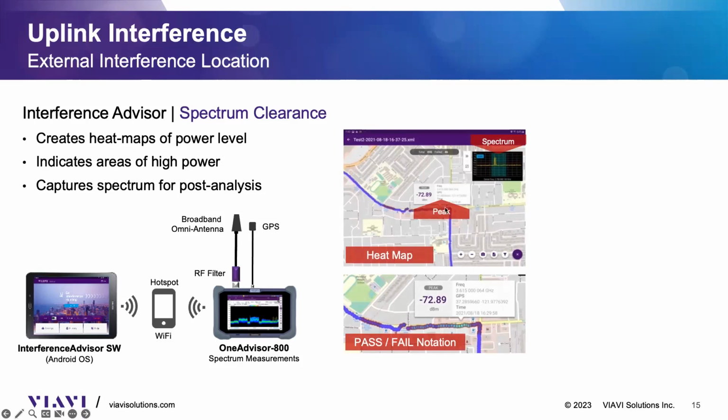Now, if something happens, meaning that if we have a signal that goes beyond a limit that we define, let's say we define -100 dBm as my limit, that everything should be below that power level. If anything goes beyond that, then we indicate the power level and put a red circle indicating that we had a problem, we had an alarm.